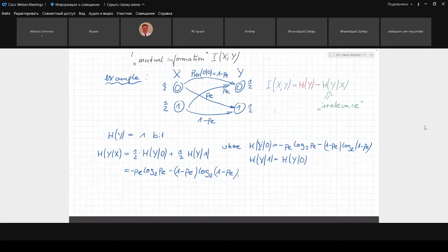Until now, we only talked about discrete channels. A discrete channel would be obtained from a waveform channel simply by doing demodulation with binary detection. If you're familiar with modulation schemes, in the simplest case, if I use a copper cable, I represent a binary 1 by a rectangular pulse, maybe by a sine wave with a finite length, and represent, as a simple example, a 0-bit with a negative pulse.